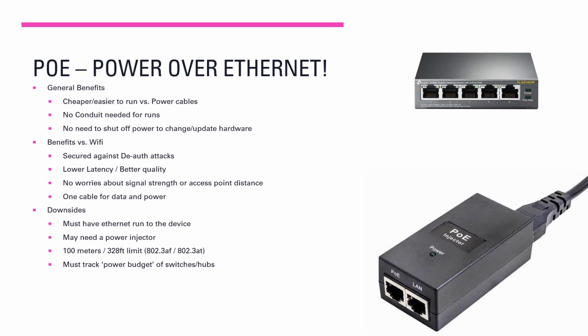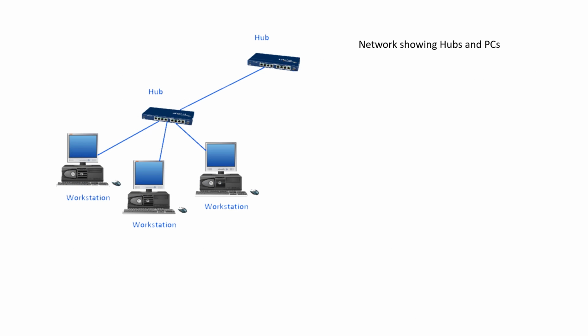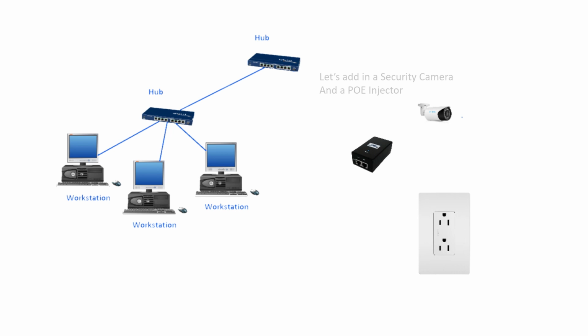The way you can do this is you can either plug it in the wall, standard 12 volt wall wart plug or whatever, or you can send power over your Ethernet connection, so you end up with a hardwired network connection, and you send power to it at the same time. This is called PoE, or power over Ethernet. What's cool about this that I didn't realize until I got into this is I thought you had to have an entire network set up for PoE, and that's not true at all. You can have your standard wired network, and then at the very end, right where you're about to plug in the camera, you can get what's called an injector, and that little device in the lower right is what they look like.